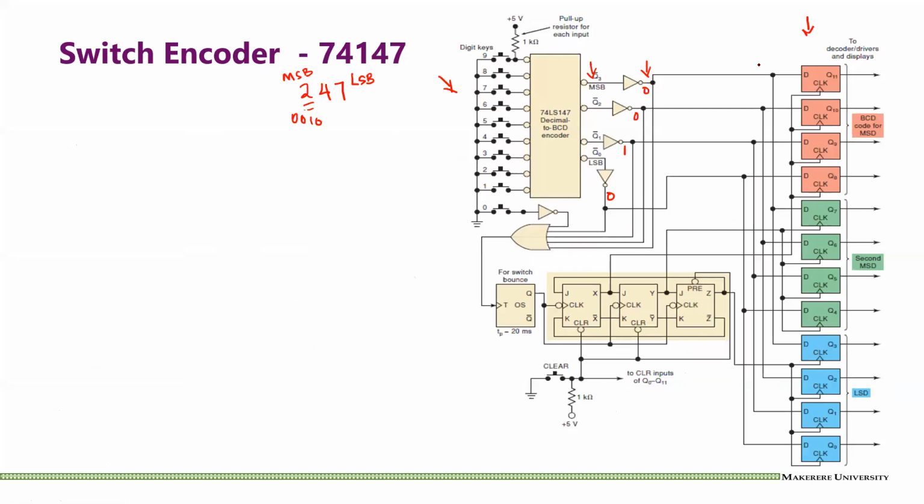Right, so I have 4-bit registers. That means I can store 2 in here. In the next one, I can store the other value. In the next one, I can store the other value. These are D flip-flops, meaning that whatever is appearing on its input, if it gets the right clock, that input will just go to the output exactly the way it is.